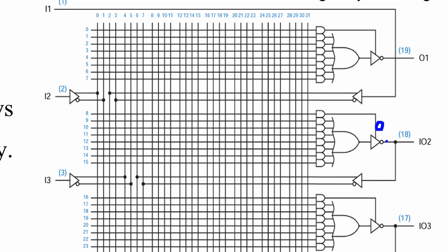That means now this output becomes high impedance or open circuit. So now you can use this terminal as an input. This input will feed to something and go to this AND gate.